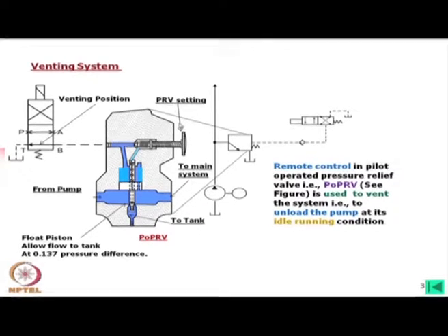Now, usually you will find that in a pressure relief valve the construction is almost the same, only there you will have a drain passage or so. This internal draining is also there in a PRV, but sometimes external draining will be there. However, another important thing is that whatever the pressure on this side, that will try to pull this one, because if you think of the load balance, this side load and this side load, that is a differential load which we are balancing on the piston.